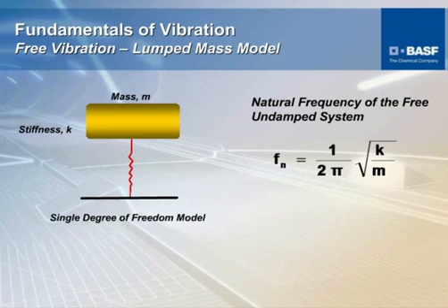All systems have an inherent natural frequency. That is, metal, wood, plastic, any system that exists has some kind of natural frequency. If the system vibrates at the natural frequencies, the amplitudes are usually very large. So in NVH or any type of vibration reduction design, the engineer or the designer should devise ways to make sure that the excitations of certain structures are done away from that natural frequency. Now, there are ways of extracting these natural frequencies, and we will talk about that specifically in other slides.